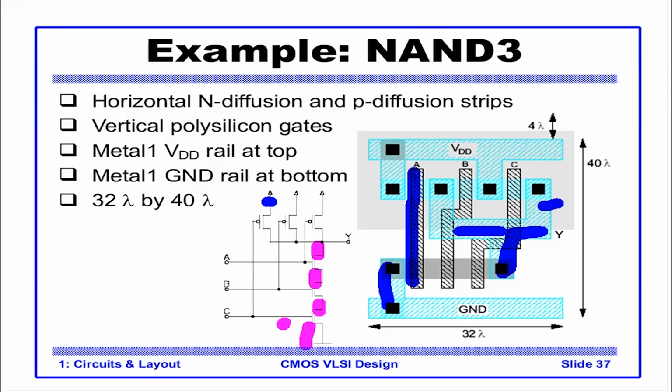So we see that very intelligently VDD connections to all PMOSes and the output connection to all PMOSes, the connections for two transistors have been shared. This is to make sure that the number of contacts remain minimal. We will see one example later. Now the height is 40 lambda, where lambda is the feature size.